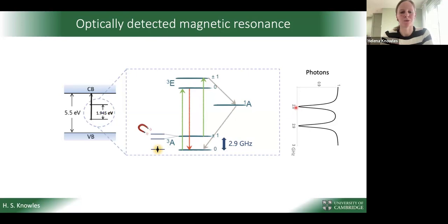So this is an example for magnetic field, but it turns out temperature, through the expansion and contraction of the diamond lattice, also gives us a change in these energy levels. They shift in a slightly different way. They don't shift apart, they shift up and down, which allows us to distinguish those two external perturbations, which is the basis for some of the multimodal sensing aspects. So we can really distinguish which external parameter changed in a given instance.